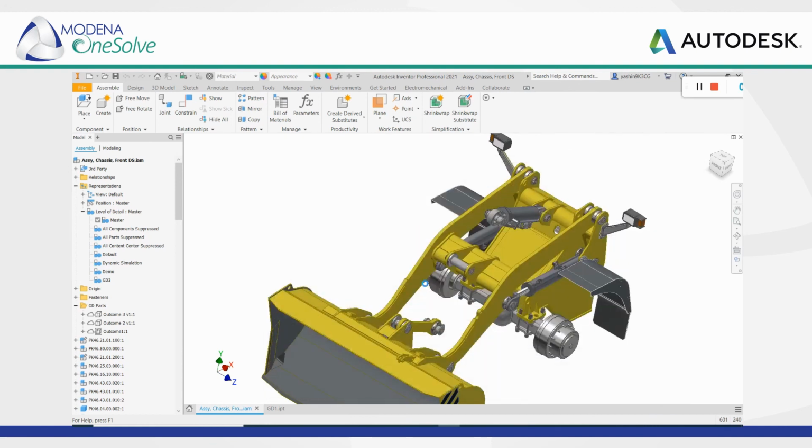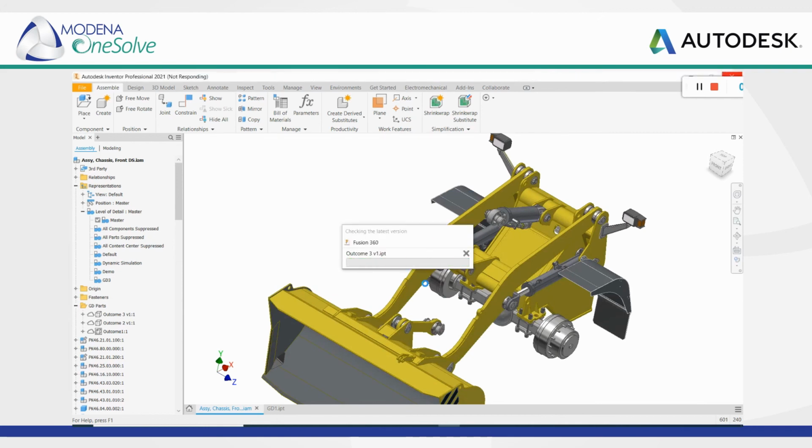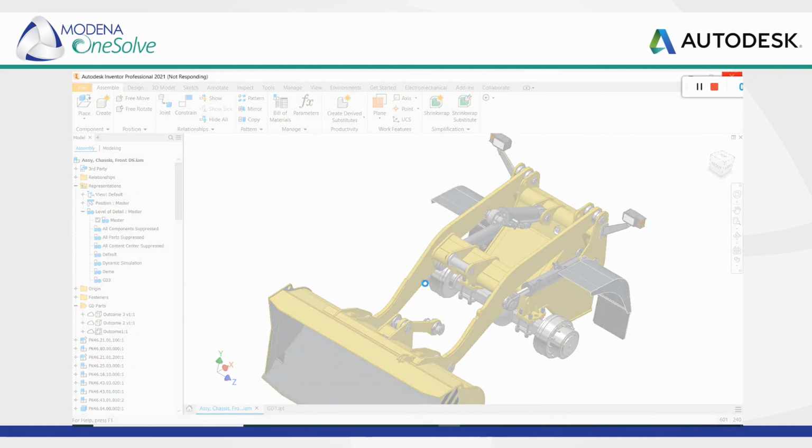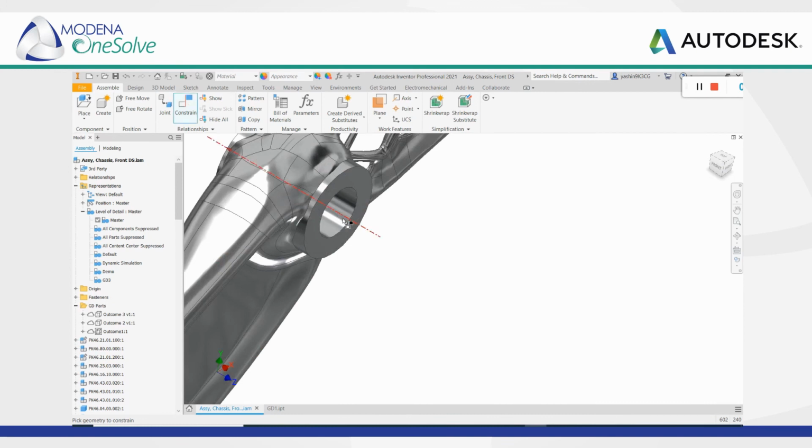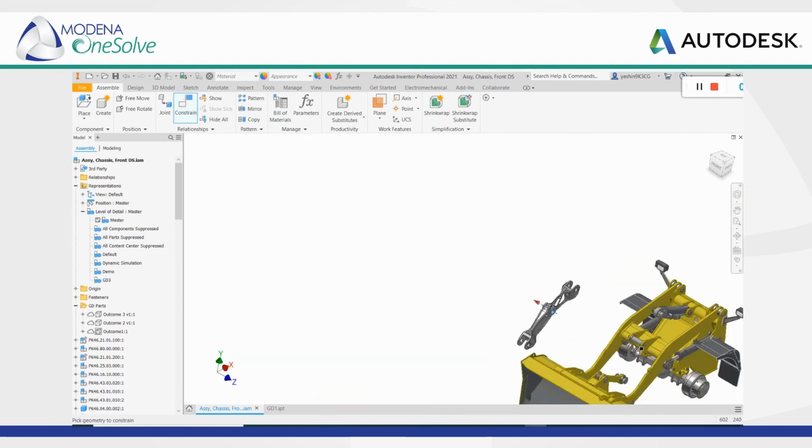So what I can do from here is bring that component into Inventor, place and constrain it. It will take a couple of seconds to load, of course, because it has to download some information from the cloud and bring it back into Inventor. So what it's doing over here is converting it to the latest version, and a readable format that can be used inside of Inventor. And as you can see, I can then place that component, and of course I could then constrain it in place.